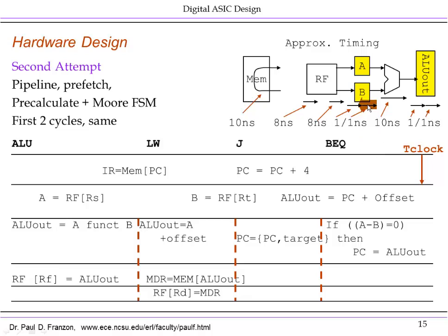That is, for example, reading this register, which takes 1 nanosecond, doing the ALU operation, writing to this register, which also takes 1 nanosecond. The path through the memory takes the same time, which, by the way, is one reason we're going to end up putting registers either side of the memory, on the address port and the data port.